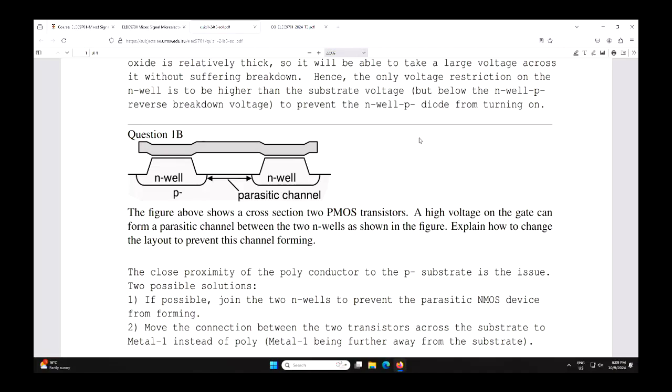This is a normal solution also to these 2. But what you've got to do with high voltage, you've got a problem with high voltage. You've got to reduce the field. You've got to make the distances bigger. That's essentially what you have to do.